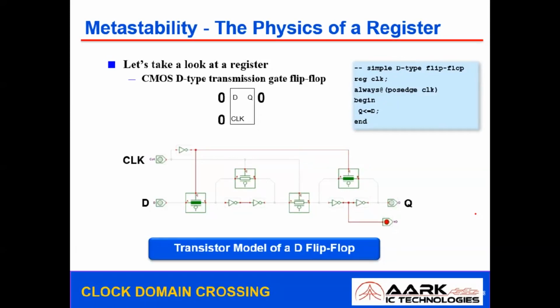Which defines the two latches which are cascaded together, and the first latch is operating at clock equal to 0, and the other one operates at the clock's other phase. So if both the latches are connected in this fashion, and both the clocks are out of phase, then it is nothing but a flip-flop.